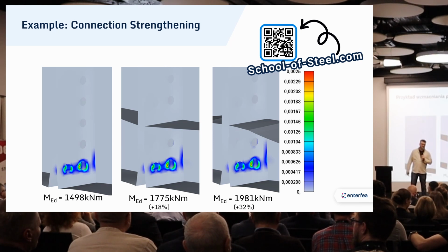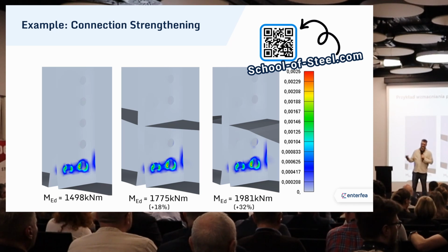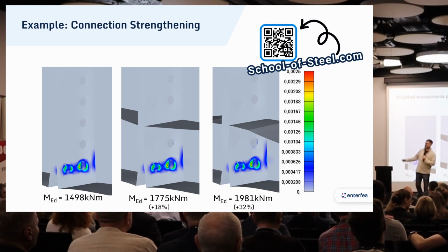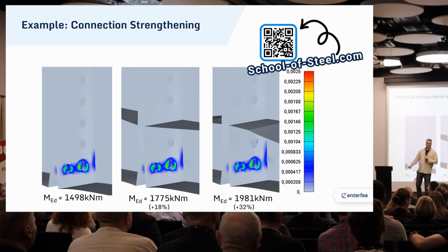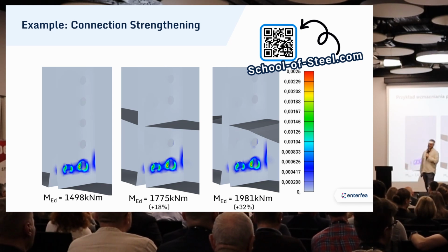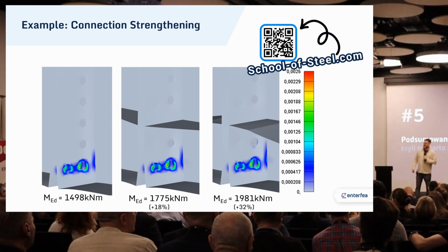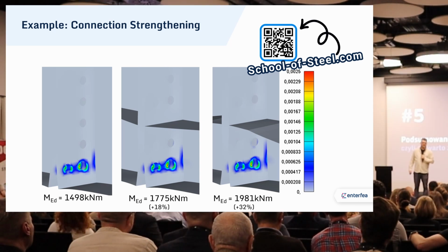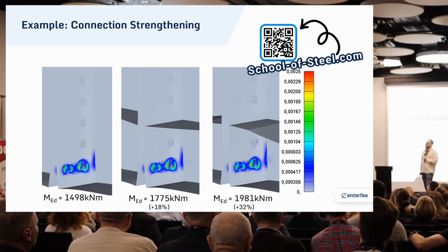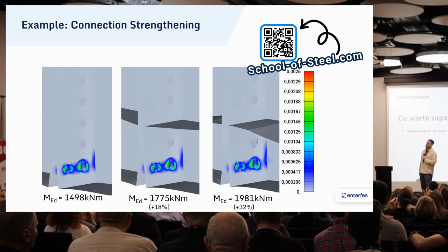However, in our other Eurocodes, for instance, for shell or plated structures, usually values around 4-5% of plastic strains are accepted. And while in connections I perhaps would use a lower value, just to take into account the simplistic approach to modeling we had to use to make the model doable, I still think that the values we obtain, which is less than 1%, are absolutely fine.